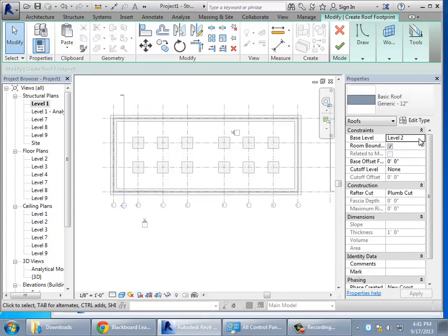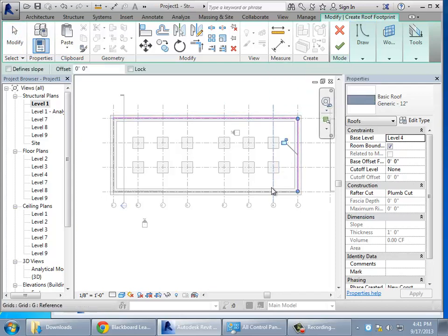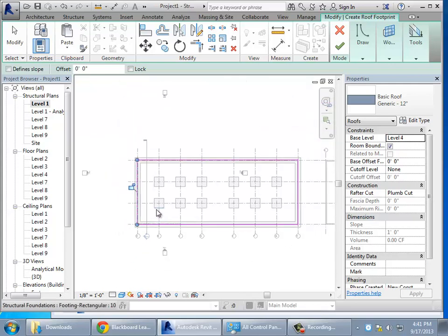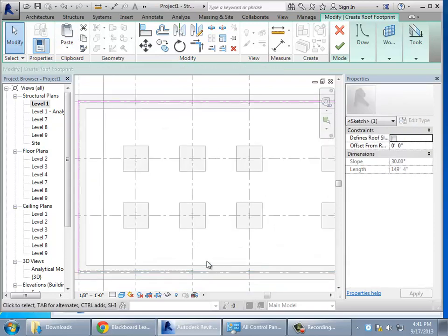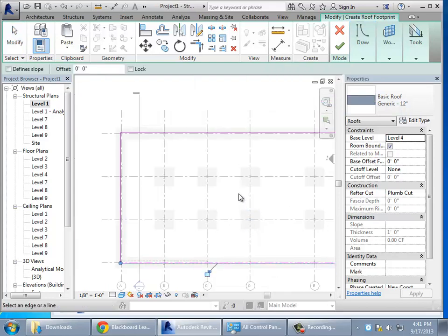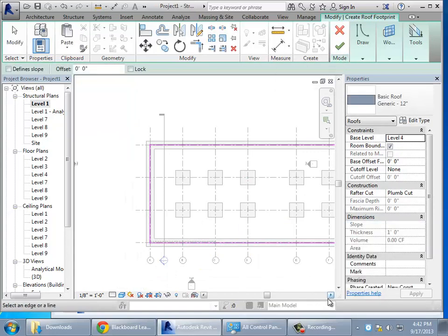When you put on the roof, it's going to be at some level. Let me put it up at level 3 now, or level 4, whatever it is. I'm going to draw it. I'll pick these lines at the outside. Your architecture modeler is going to do a much better job than I'm doing right now, but it'll at least give me something to get started with. Okay, that one's actually on the wrong side. This one over here, the outside. Okay, let me try finishing that off. It's not quite in the loop. Let's get that fixed up.